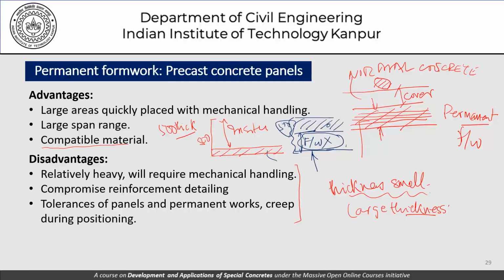So this has to be taken into account from the economics point of view, not only the initial cost of construction, but also considering the life cycle cost. So obviously if a structure is more durable, the life cycle cost will be lower. There will be lower issues related to maintenance, and that could possibly justify the investment in permanent formwork, or for that matter even the CPF liners.